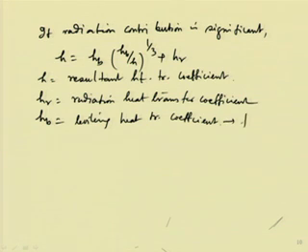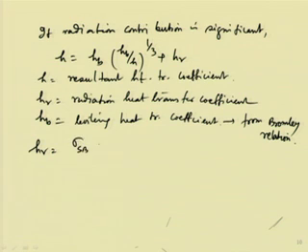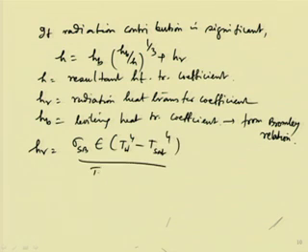This is from the Bromley relation, and Hr is obtained as, say, sigma Sb epsilon Tw to the power 4 minus Tsat to the power 4 by Tw minus Tsat. Here sigma Sb is called the Stefan-Boltzmann constant.